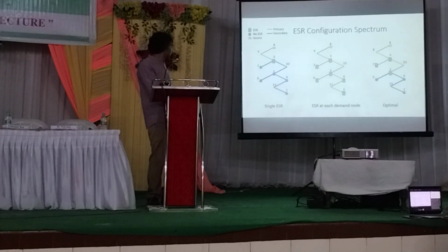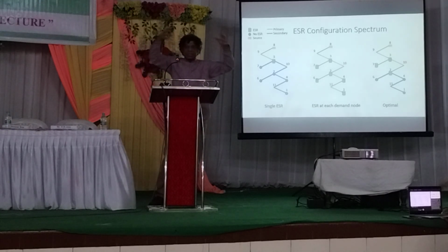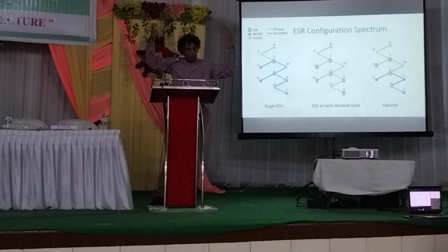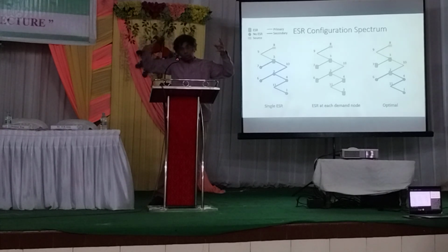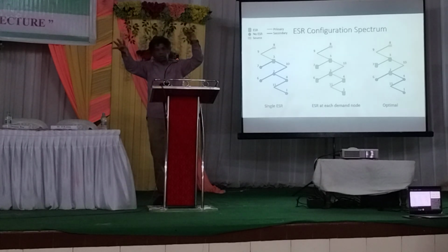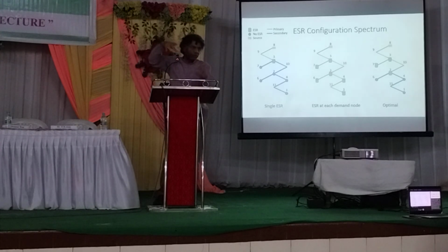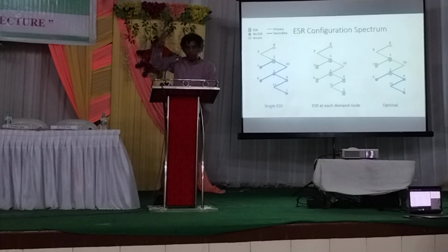Next. The main point, I will skip the detail, is that if you increase the number of tanks, your tank cost goes up, but your pipe cost goes down. So there is a tension. When one cost is going up, the other cost is going down as you move from one tank to a tank in every village. So clearly there is a point in the middle, which is the right point, where these two costs balance out, and that is the optimal point.